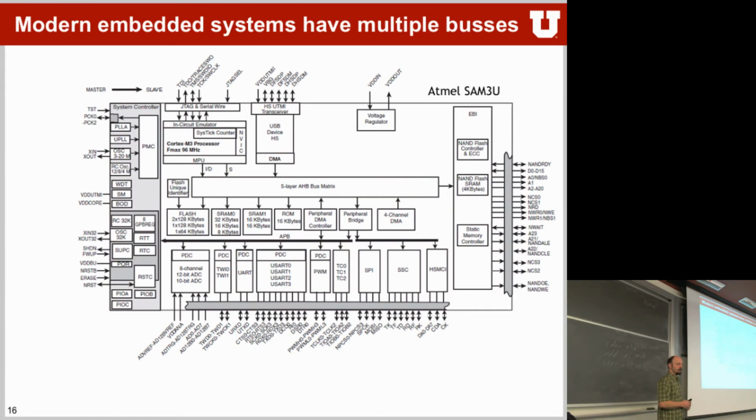If you look at a modern microcontroller, there are a lot of different bus systems out there. Oftentimes, the legacy buses that get talked about in embedded systems courses are the ones here on the side, which are external memory interfaces, so how you hook up to NAND flashes and SDRAMs. Down here, we have a lot of different serial and parallel buses to talk to, for example, SD cards, SPI buses, I2C, other serial buses, parallel buses. These are all external buses that usually go off chip.